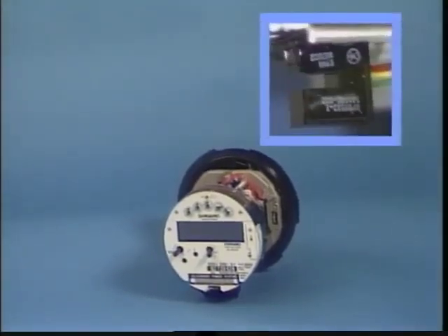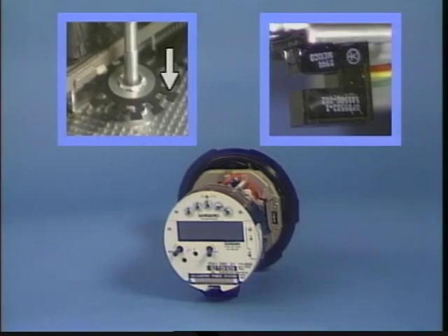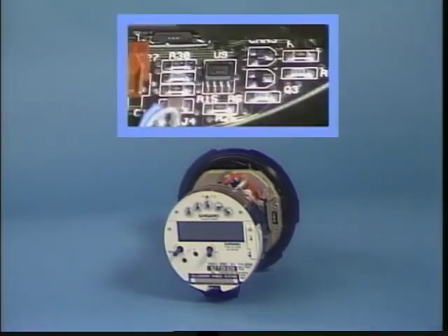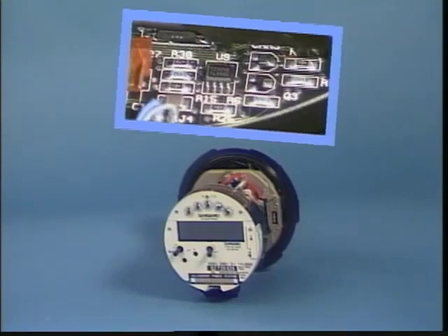For example, this meter uses a photo-optic assembly. One part of the assembly contains a light-emitting diode. The other contains a photocell that senses the light. The two parts of the photo-optic assembly fit above and below a vane, or shutter, that is mounted on the meter's disk shaft. As the shutter rotates with the meter disk shaft, the shutter intermittently interrupts the light path between the diode and the photocell. This generates pulses that are counted and stored by the microprocessor. The faster the meter disk and shutter turn, the more pulses are generated, counted, and stored during the demand interval.